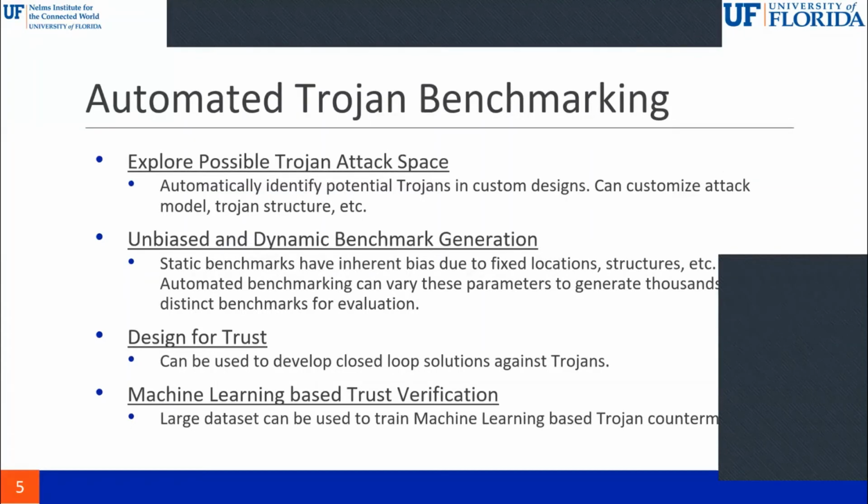Again, if we have static benchmarks, the problem is that, while they're good for comparing different techniques, developers might start to tune their techniques to detect these Trojans only, and given that they're not entirely representative of the entire Trojan space, which is generally very large, this could be problematic. We can mitigate that by quickly exploring and generating thousands and thousands of distinct Trojans for different threat models and the like for evaluation.